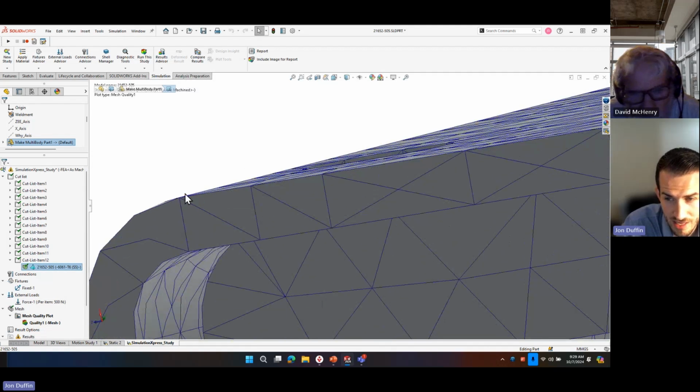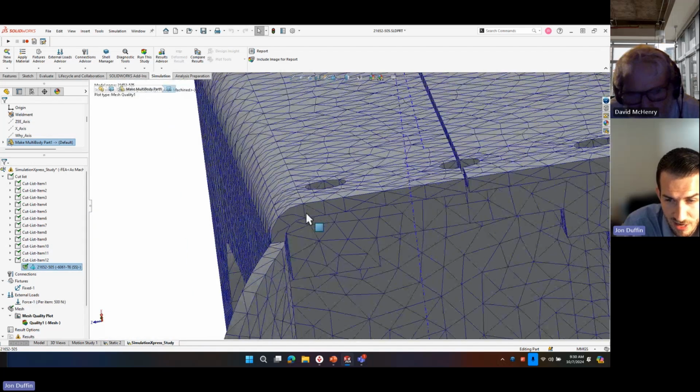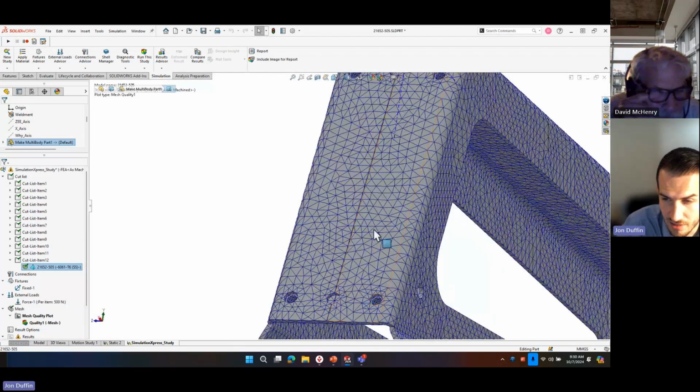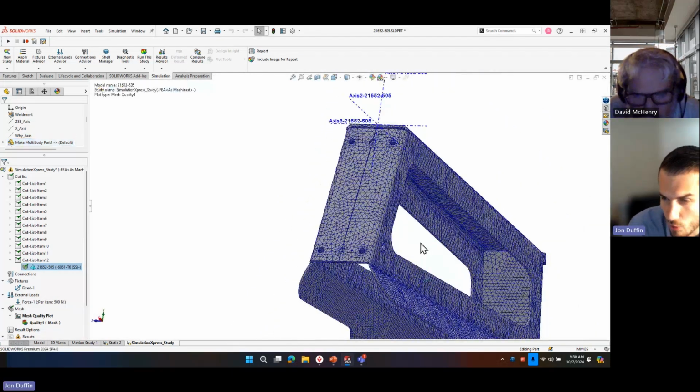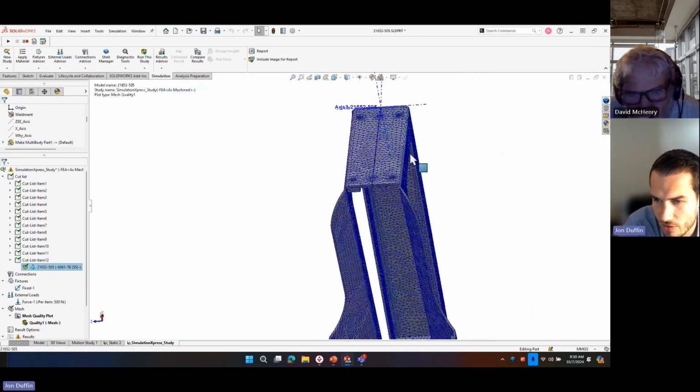And right now, it looks like there's one a little bit distorted. So some of your bending loads and things like that, those results would be more off the thinner it is without having two elements through the thickness.